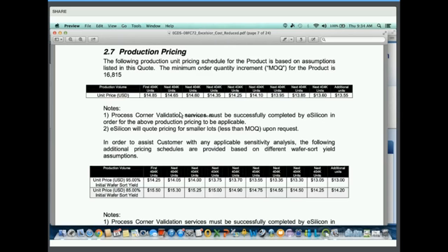If you think about it, the number of options to tape out a chip in a TSMC process node is rather staggering. There's lots and lots of data. And the way we managed the information explosion and made the user interface more manageable is by doing exactly that. So as you go through the menus top to bottom, you're limiting your choices in the earlier stages so that the things you see later are only the things that matter or make sense for what you've requested earlier. So that's actually good for two reasons. Number one, it reduces clutter and reduces the complexity. The other important point is, with this interface, you can't request something that's invalid.